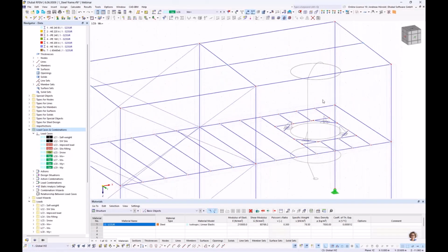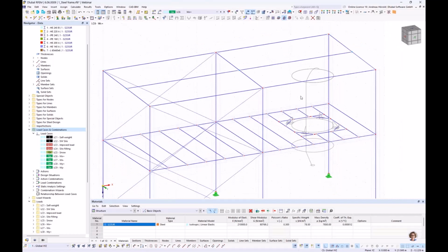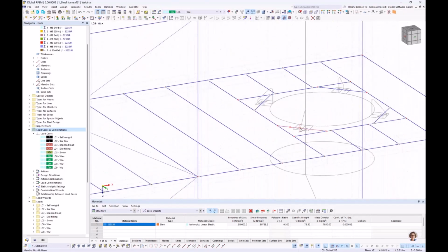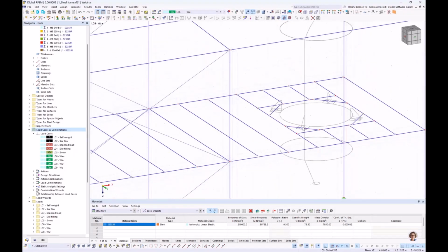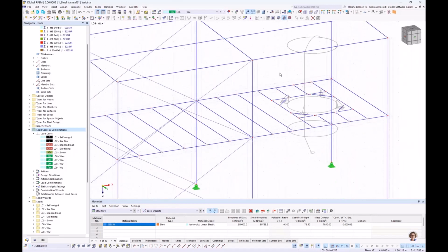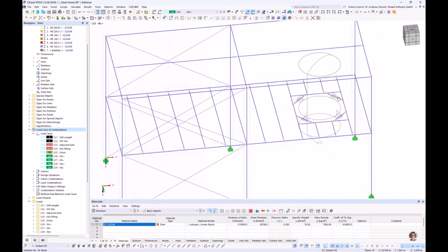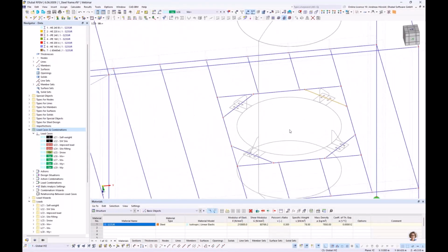That's in that area a doubled load, but I would like to consider also the horizontal load at the beams and also the vertical load from the wind that we get from the moment that we get from the wind on the silo. So I start with the wind in X direction. So that's a good view.